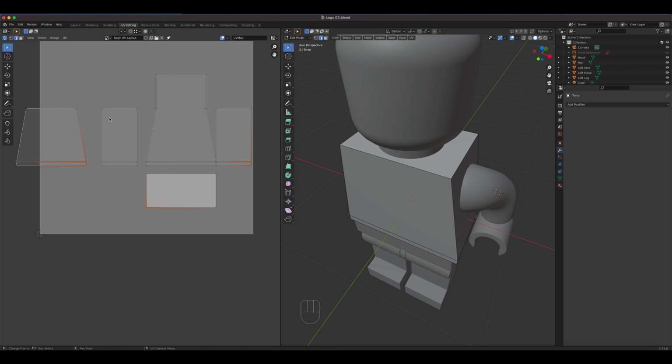So, it's easy to flip these things. You just simply do an X -1. If I select this one here, and this one as well, and press S to scale along the x-axis -1, press enter, and that's flipped already. Now let's check it. If I select that side, it's now saying that that's the correct one. That's where this one is supposed to go, right?